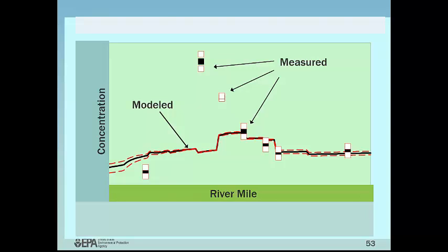And you hit run the first time, and it might be a little disappointing. And it's possible that only the modeler sees this result, because he or she is going to get to work to make this better. But the solid line is modeled, the squares are measured, and we're in the ballpark, but it isn't that great either. So we might call this the initial error of the model. Now we're going to work on it. We're going to do calibration and troubleshooting and see if there's reasons we're this far off.